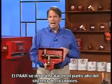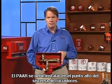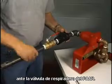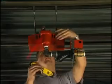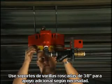The Potter automatic air release should be installed at the high point of the fire sprinkler system. Begin by installing a ball valve and strainer before the air vent valve on the PAR. Now install the PAR, making sure it is level. Use 3/8-inch threaded rod hangers as needed for additional support.